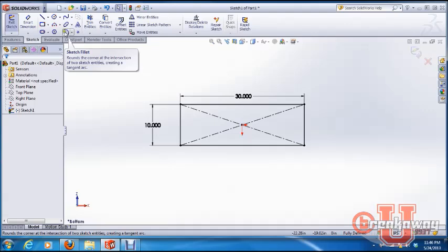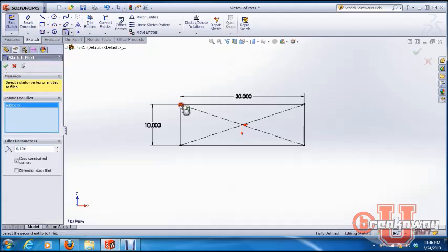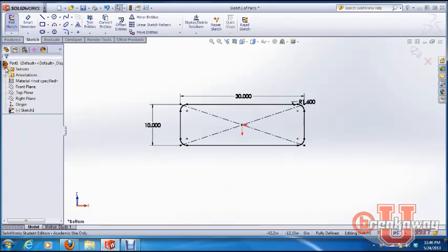It's real simple. If you want to create a rounded corner, I can show you right now. You just click on it, go to that corner, and there it is. You can't see it, it's kind of small, but I'm going to select all the corners, and then I'll go over here. Always go to your property managers when in doubt, and you can use this here. I just typically use it, and notice as I increase it, you can see the radius of that fillet. You hit check, and now look, you got a nice rounded what was a rectangle. Check, and I'm out of it.